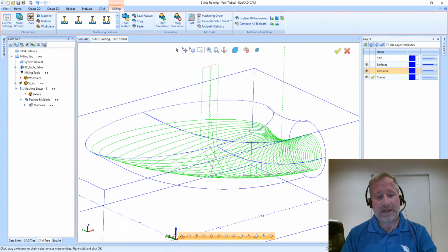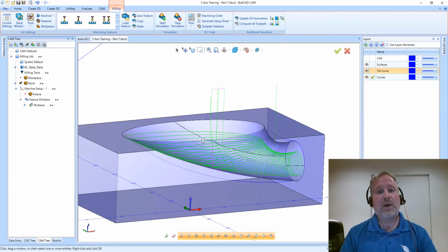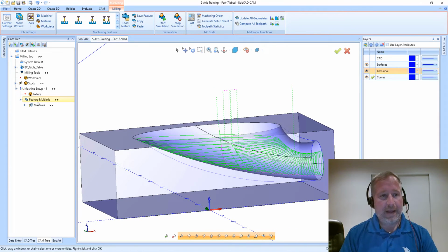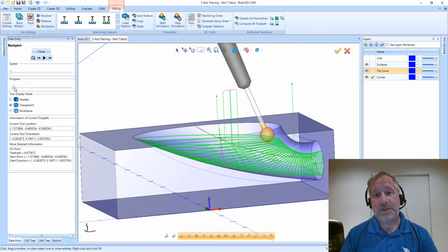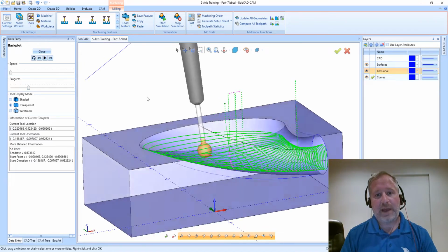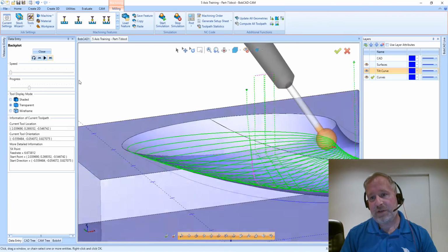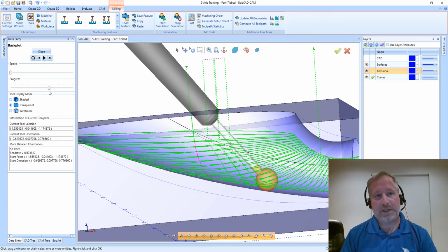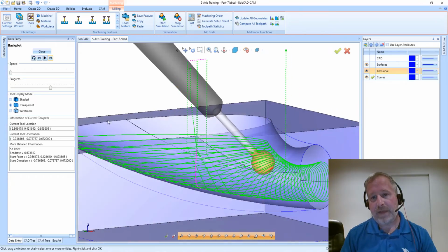So we've taken that next step and we've gotten a now clean path with our tool laying over the way that we need it to. And we can start to think about what is the next obstacle that we need to be able to create this good final path. I'm going to back plot this through, and you can see there's no longer any of those funny little jog moves that we were experiencing earlier as it transitions up the side of that port wall.